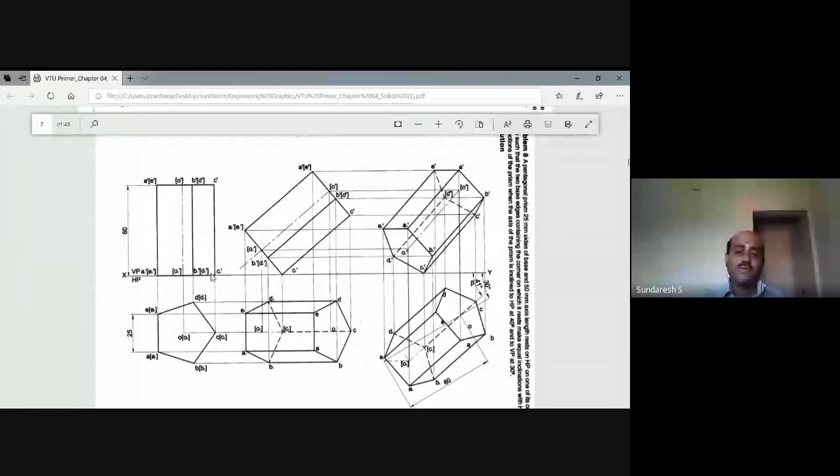and correspondingly you can get these points C1 dash and B1 dash. So C1 dash and B1 dash, take a compass, measure this distance and cut here, and you can join. And similarly the axis also. So take the distance from C1 dash to O1 dash, mark here, and C dash to O dash, mark here, and then you can join. So once you get the outline of a front view, then correspondingly taking and measuring the distances with a compass from the initial position front view, the same points can be transferred in the second position front view.